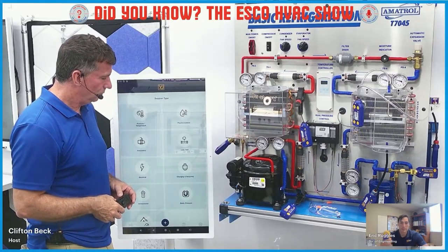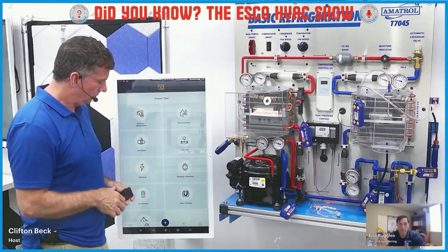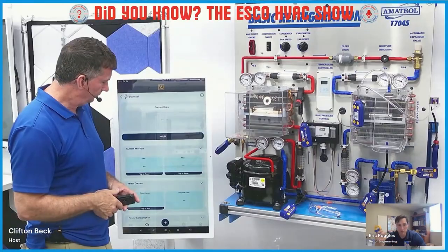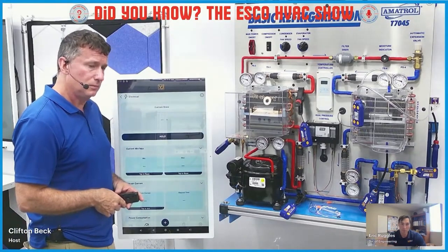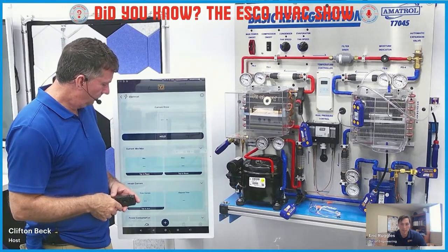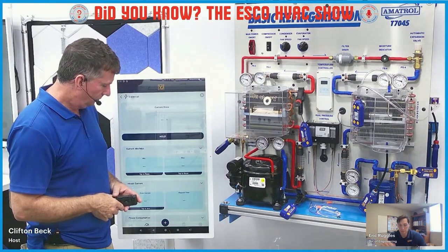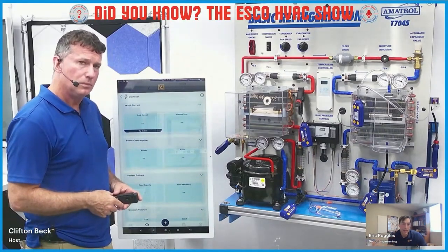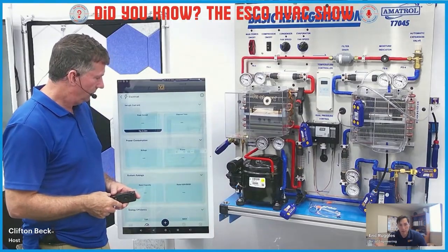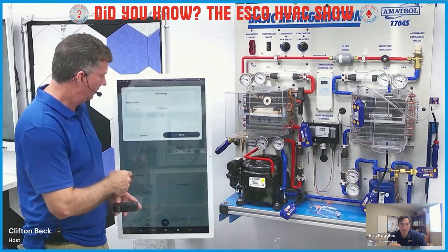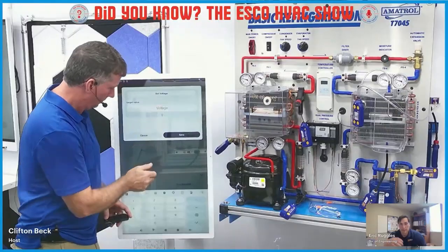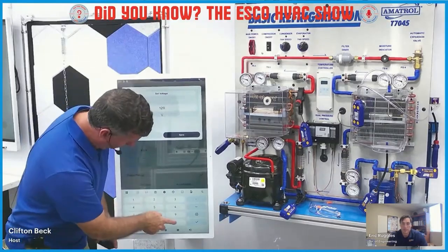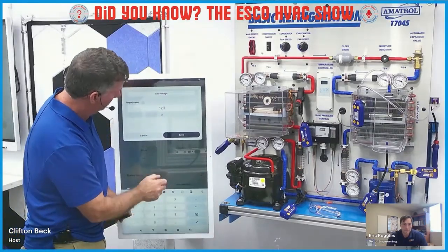Electrical session is with the amp clamp. So if you click into that one, if you have this on a system, it'll show you basically what the amps are reading. It'll also show you an inrush, if the compressor jumps on, how high that is. It'll track your maximum and minimum values during the whole session, and you can take a snapshot of those values and add it to your report as well. So you can typically take a snapshot of the compressor, the condenser fan, the evap fan, to show what they're doing. You can add in the voltage, so then it'll automatically calculate what the power is running and then how much that's actually using on the system. Then it'll auto calculate how much energy the unit is using. That helps you with the efficiency overall as well.